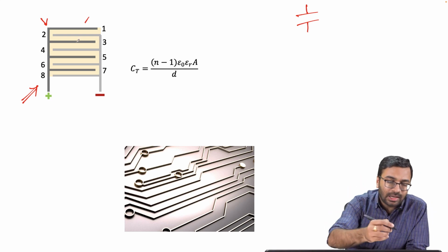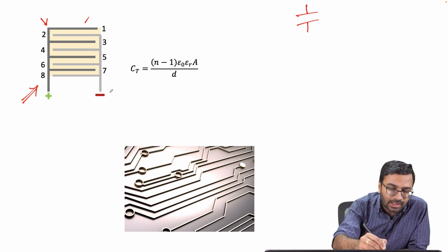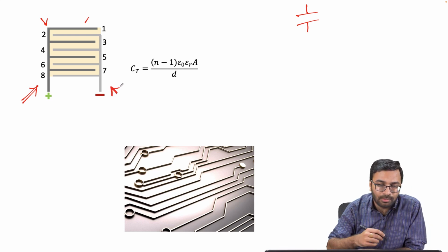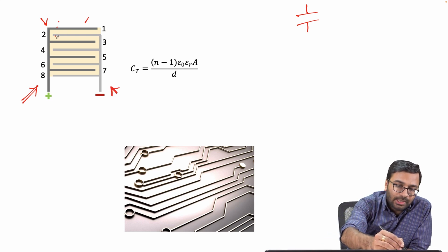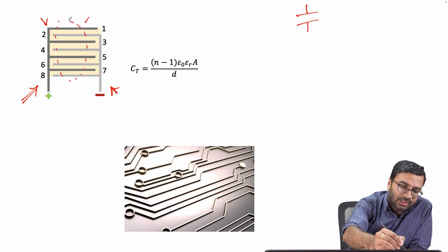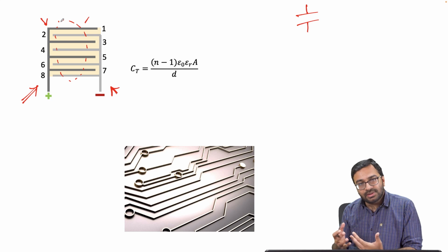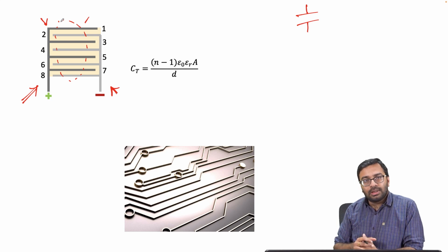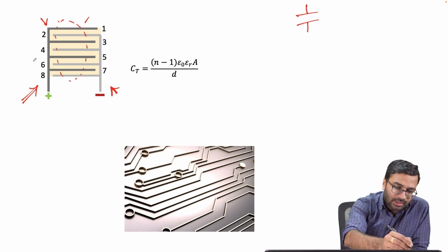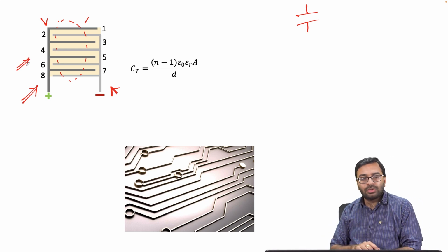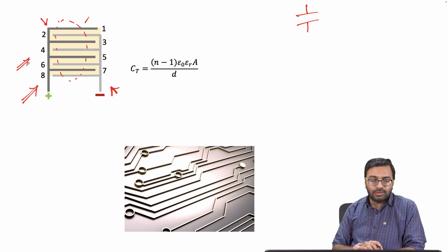In the case of resistive sensors, you will find interdigitated electrodes are very popular, because once you put material on top of this interdigitated electrode, you will be able to get a higher surface area covered using these electrodes. So this provides a better response.